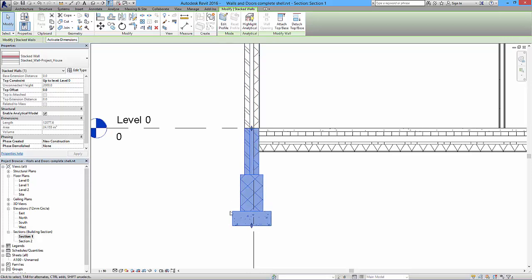And so why fill your cavity with expensive facing brick when you can fill it full of blockwork, which will do a much better job, much easier to lay in a trench, and much more suitable for the task. So that's why we'd adopt this sort of system. It also allows us to break this line at this point, so the plasterboard or the plaster can stop at the screed level.